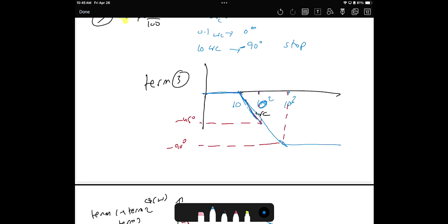And most likely we have a MATLAB plot, so MATLAB will do the whole job. Okay? So you just put the poles and zeros, then you can play with it. Then you can design the optimal or the best location for the pole and the zero based on the Bode plots to maintain a stable system, fast enough, with a good response.